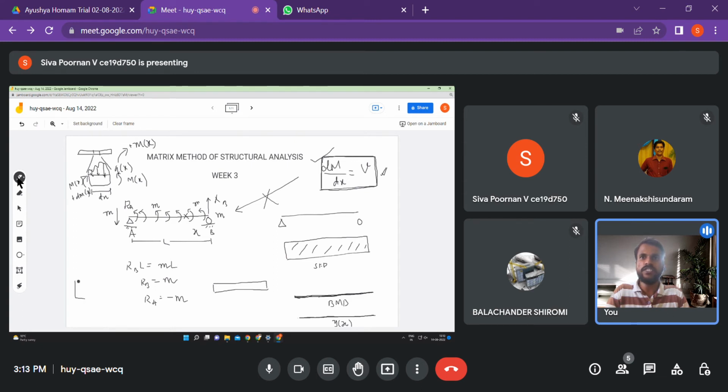You remember what will be the deflected shape of a shear subjected cube? In strength of materials you would have seen this, right? If you apply it to shear, then it will have shear deformations, right? The cross sections become tilted to the axis. Same thing will happen. This will just become like this. That's all. That is the only difference that you can see in the beam. So it's not like rigid. Since you're applying only shear forces, even though we are applying a uniformly distributed moment, internally it's subjected to only shear forces. So therefore it will have only shear strains, no curvatures.